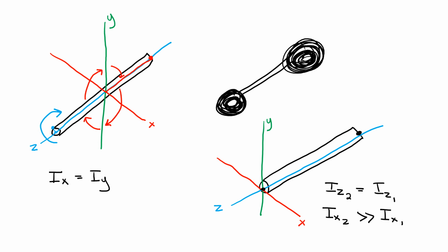For the boat design competition, we are not concerned with the mass moment of inertia, but instead the area moment of inertia. Still, this is generally the same concept. Instead of 3 axes of rotation, the area moment of inertia of course only has 2. A typical engineering example concerning area moment of inertia is the bending stress of an I-beam. So if I draw an I-beam, and this is the cross-sectional area,